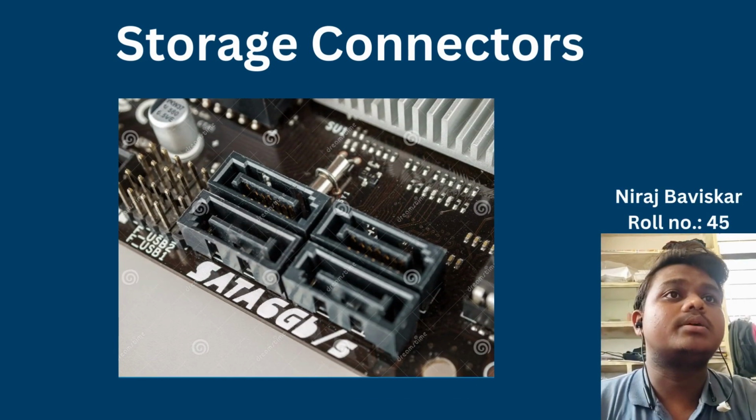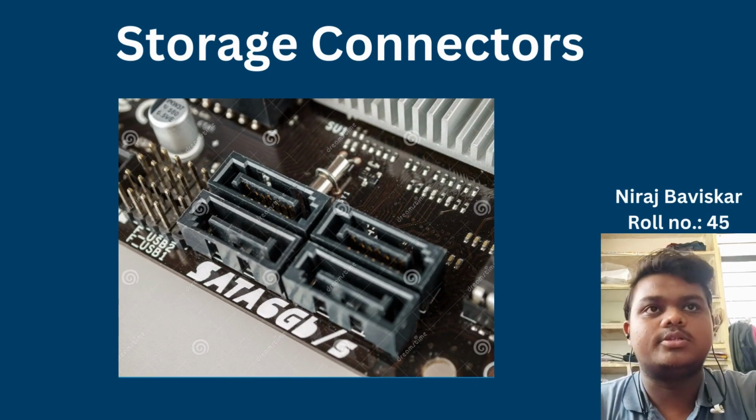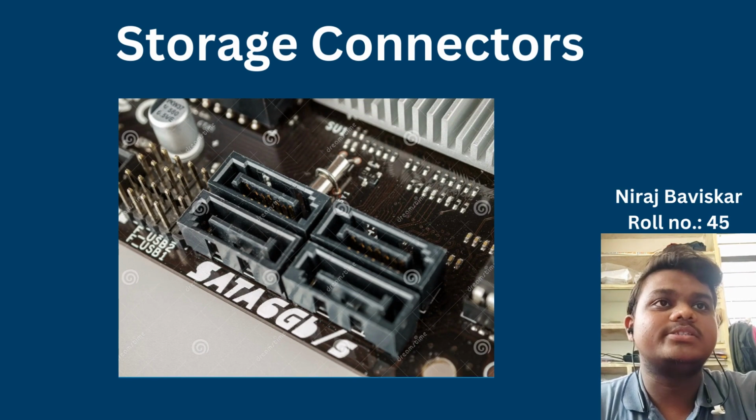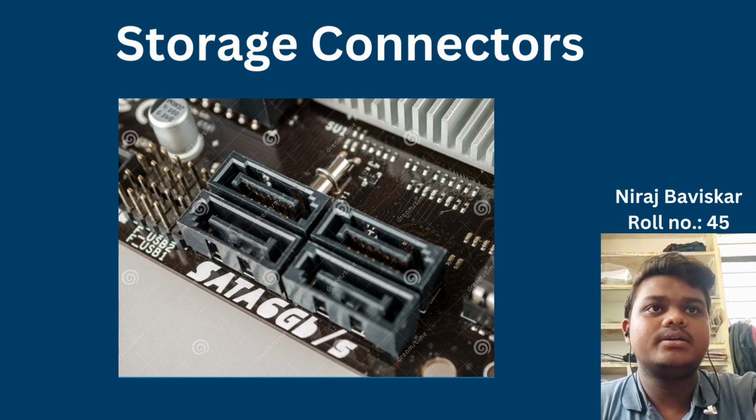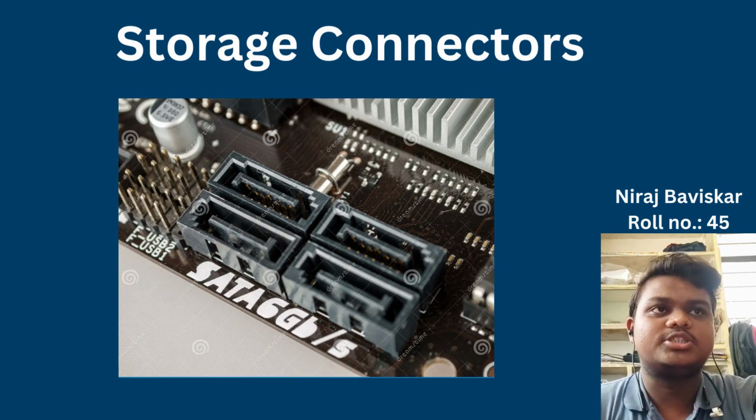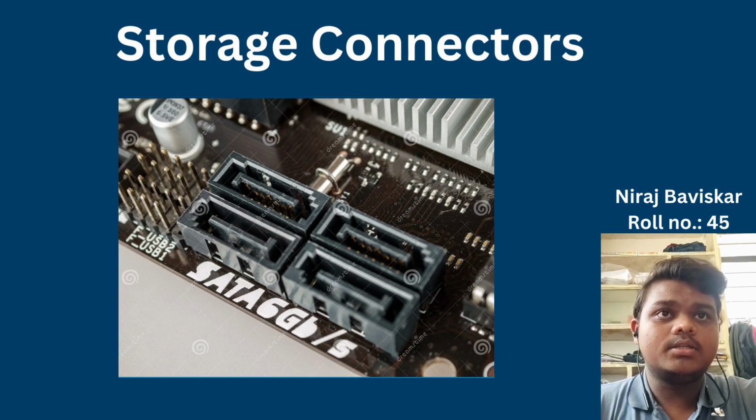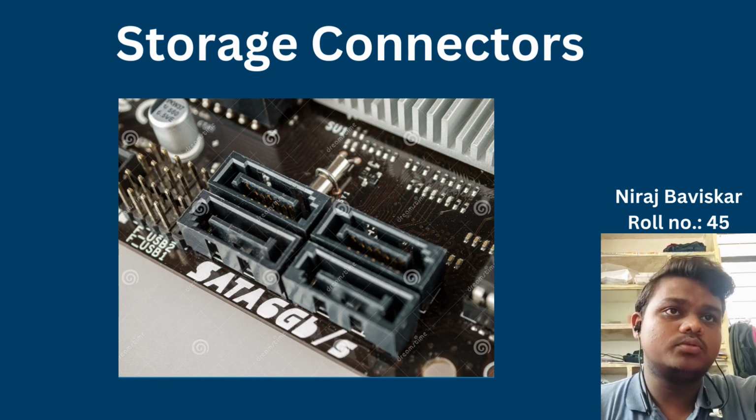Storage connectors on a motherboard serve as the interface between the motherboard and various storage devices, enabling data storage and retrieval. These connectors provide the necessary data and power connections to establish communication between the motherboard and storage devices like hard disk drives and solid state drives. The two most common types of storage connectors found on motherboards are SATA and M.2 connectors. Let's explore each of them in more detail.